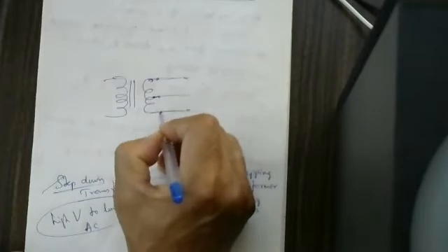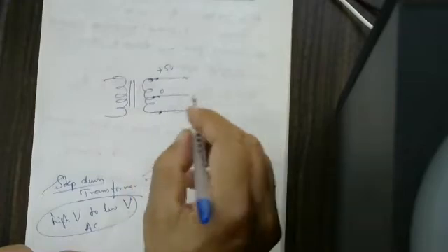I told you already, this is a central tapping transformer. If you connect between here and here, maybe you are going to get 5 volts. Here to here also, you will get 5 volts. If you connect a voltmeter from this point to this point, you will get 10 volts. Means, between here and here, it will show plus 5 volts and this is 0 volts. Here to here, this is 0 volts and this is minus 5 volts, because it is an alternating current. Here to here, the difference is equal to 10 volts.